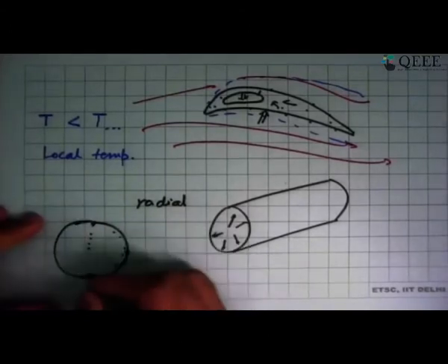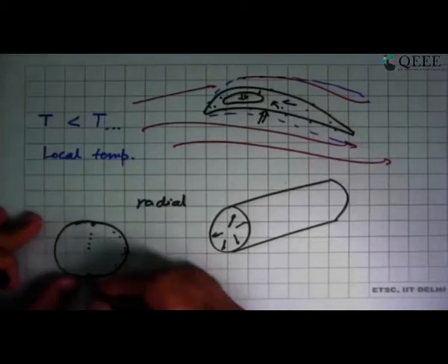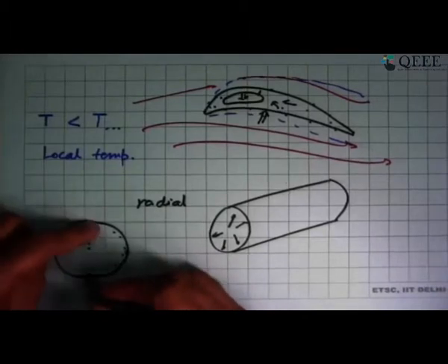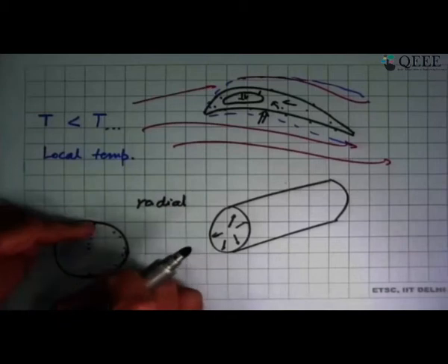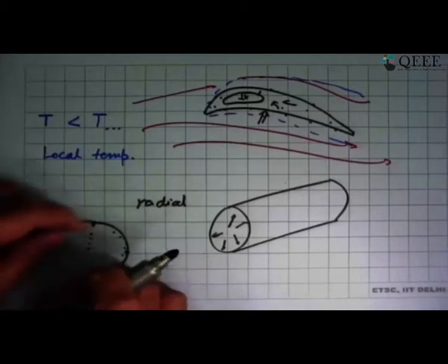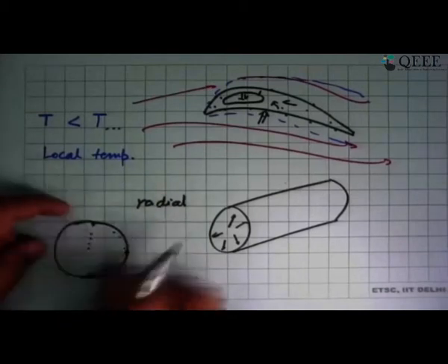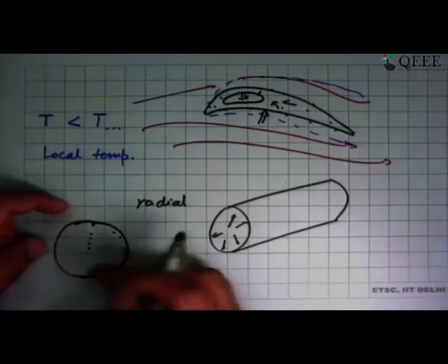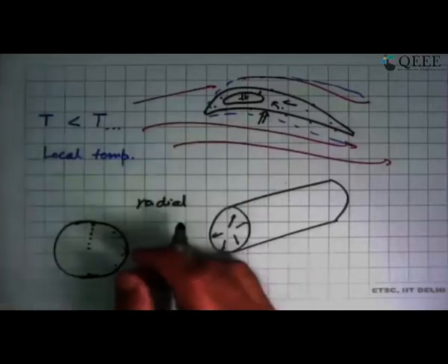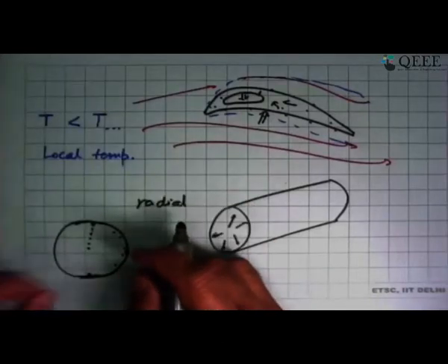So this point, its temperature will keep going down, while this one won't go down as much. Because of thermal expansion, this will start to contract, this will remain expanded, and it will generate stresses inside this material. Even due to temperature gradients like this, it will generate stresses, and chances are there could be cracks in the material.